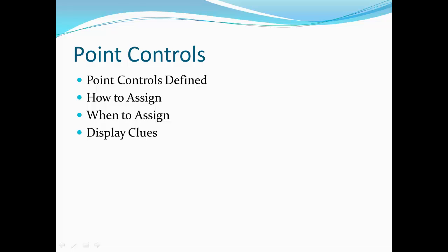When to assign. Once again, point controls are the most powerful tool in Roadway Designer. They allow the manipulation of any point on a template regardless of any other constraint, definition, or rule. They are best used for superelevation, complex transitions to other corridors, independent ditches, intersections, and manipulating null points for display rules.